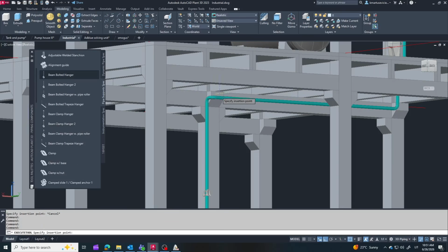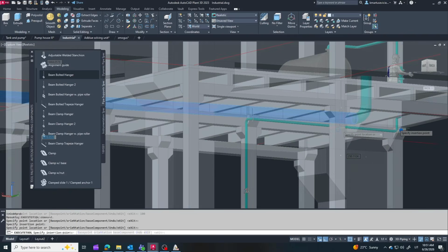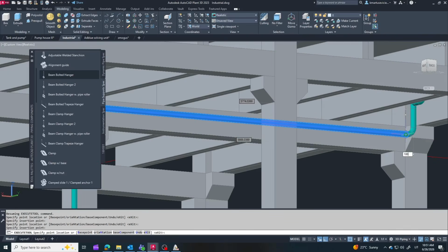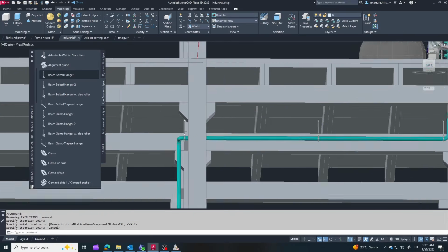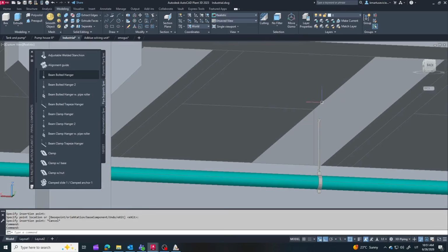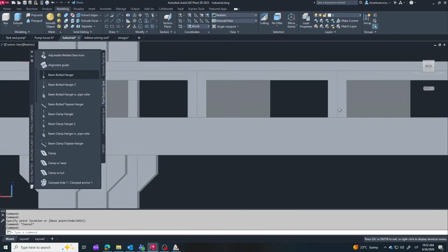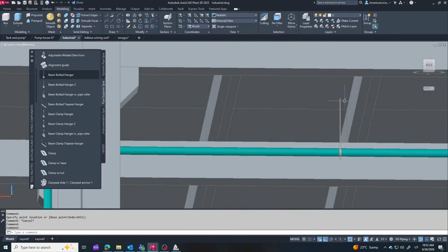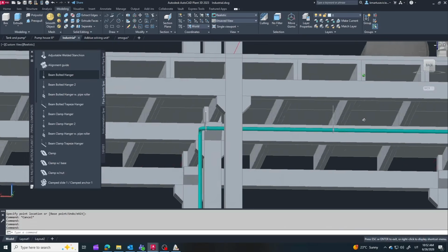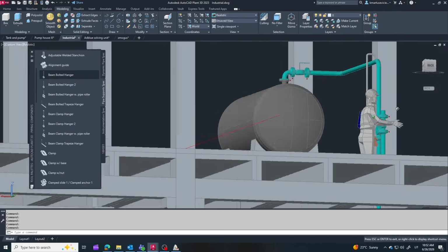This is one of my favorite pipe supports, a hanger support. It's simple, effective, and especially useful for piping located at higher elevations. As long as the building structure can carry the load, it's usually a very practical solution. From the structural side, this type of support is usually quite simple. The structural engineer only needs to provide a steel plate or embedded plate with a hole for the hanger rod. The rod is then secured with nuts and washers to support the piping.